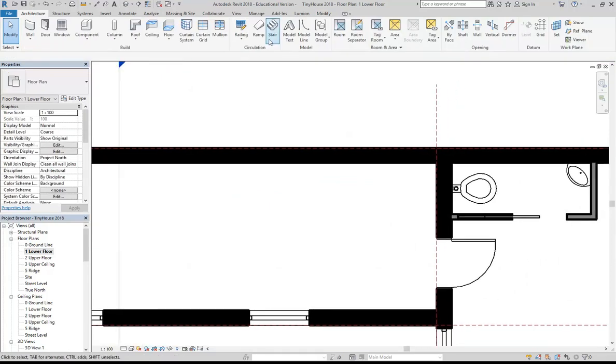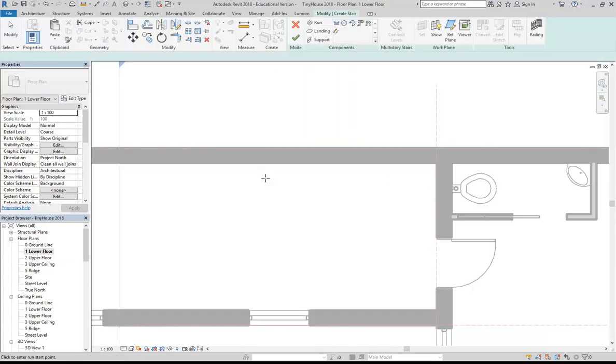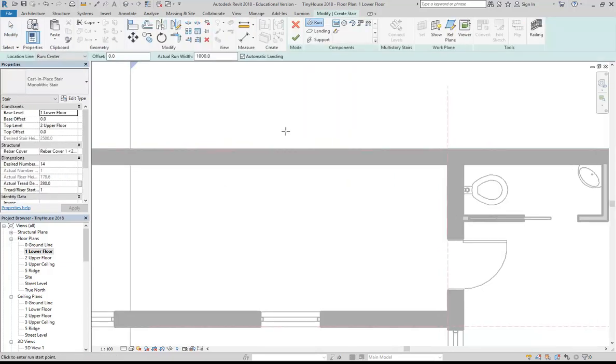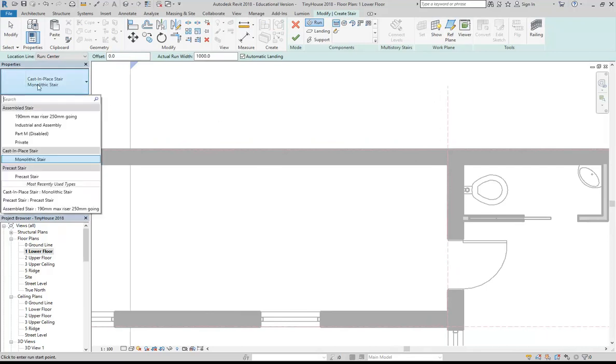And so now on the Active tab, I'm just going to click on the Stair tool. I'll point out a couple of things before I even start drawing. On the left, you've got these different stair types, and they do draw differently. The one you probably find most difficult is the concrete stair. There are two types of concrete stairs: the cast-in-place stair and the pre-cast stair.